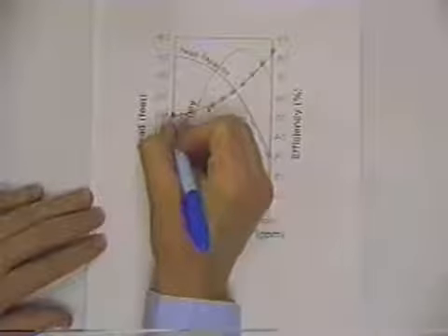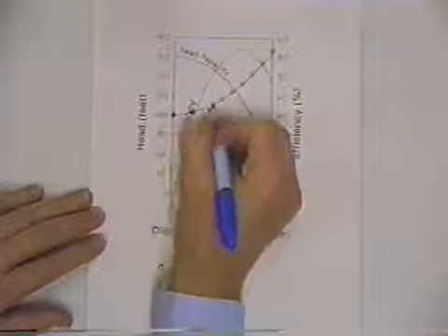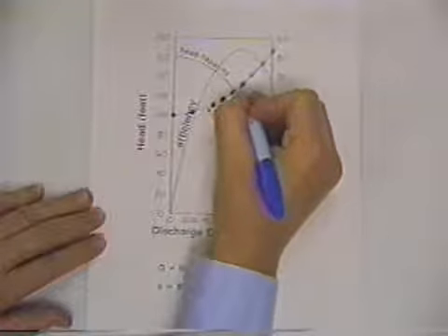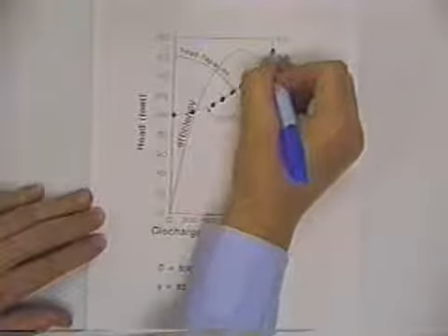And so if we wanted to illustrate it in the graph, we would just say for different Qs, and the graph's in gallons per minute, so the Qs are in cubic feet per second, conversion factor. We can plug in the Qs and get the pumping head. And we just computed these points. And those points represent the system, taking the concepts that we've used in other examples just a little bit further.